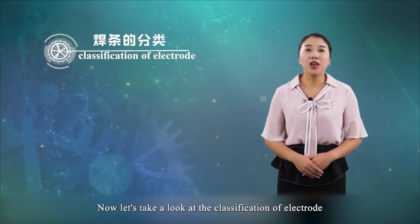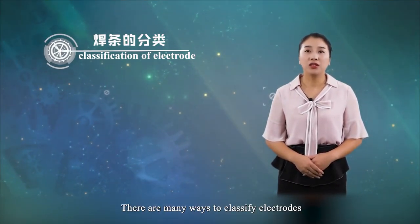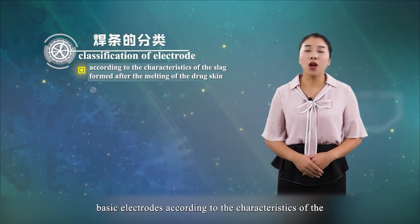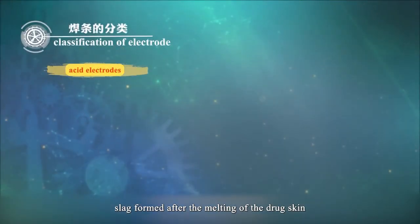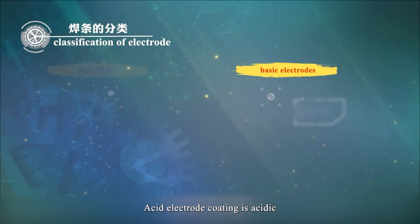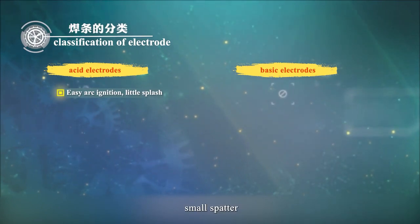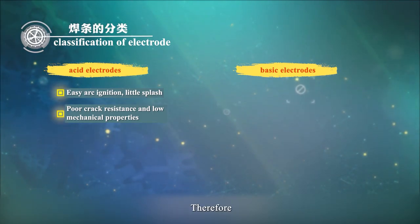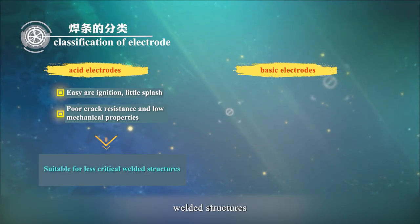Now, let's take a look at the classification of electrode. There are many ways to classify electrodes. We mainly learn the classification of acid electrode and basic electrode according to the characteristics of the slag formed after the melting of the coating. Acid electrode coating is acidic. Its main features are easy arc ignition, small spatter, but poor crack resistance and low mechanical properties. Therefore, acid electrodes are generally suitable for less critical welded structures.